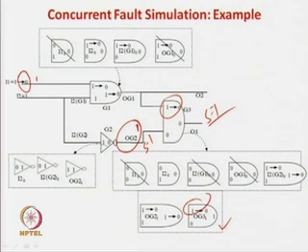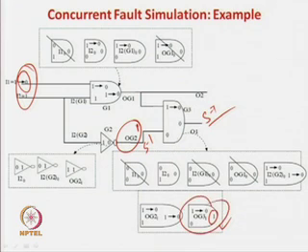So you write like this, and the gate which corresponds to O1 stuck at 1 is still retained because there is a signal difference, just because of this change application. So, it will become 0 0 0 in the normal case, but if it is stuck at 1, the answer here will be a 1. So, by the previous computation only you can say that this gate is retained.